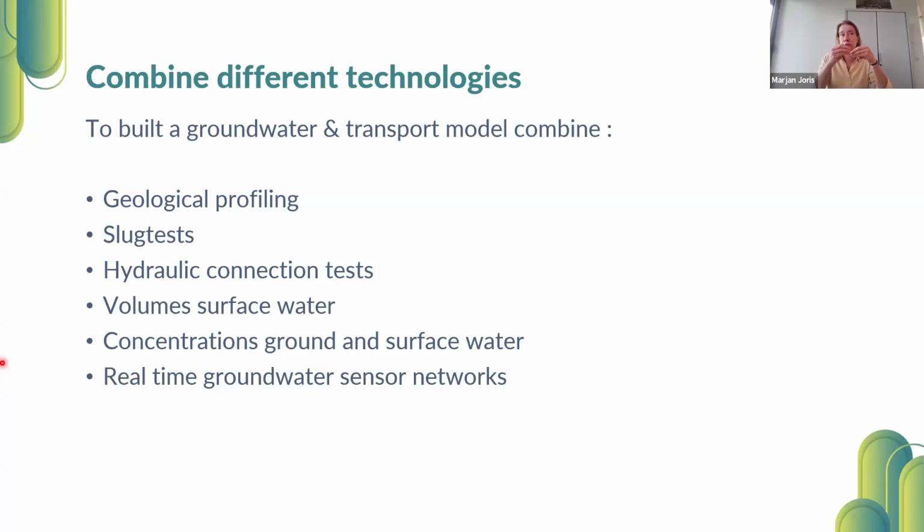This is especially important for the groundwater cartridge, because the tracer alcohols will elute. It can be that they elute during installation. And if you go to a depth of 50 meters, part of the tracer alcohols may already have eluted by installation. So we perform additional testing for that, and we correct the results with the help of these tests.